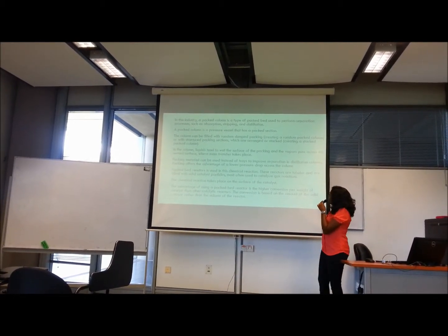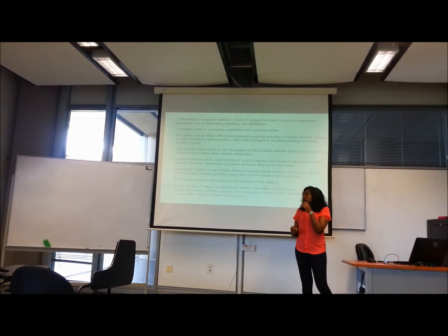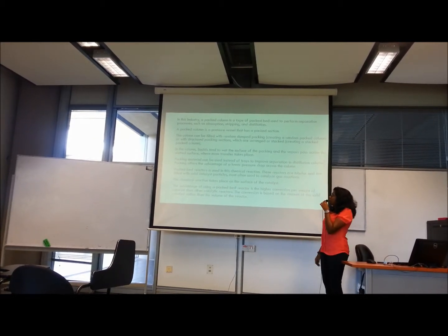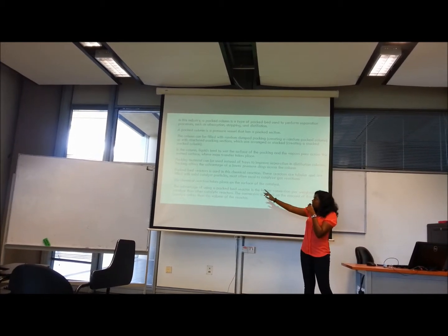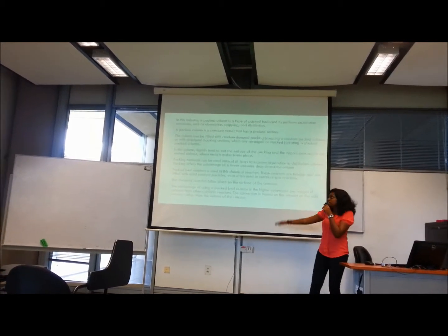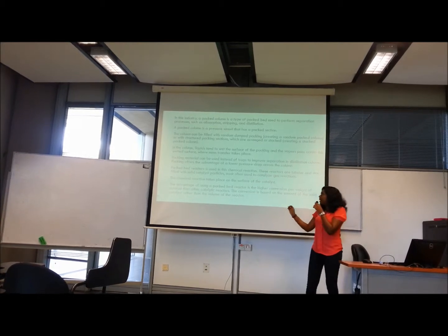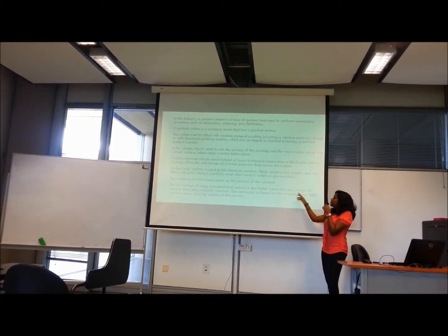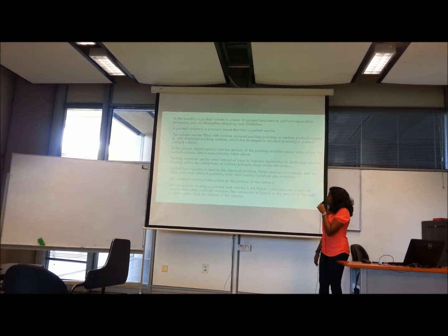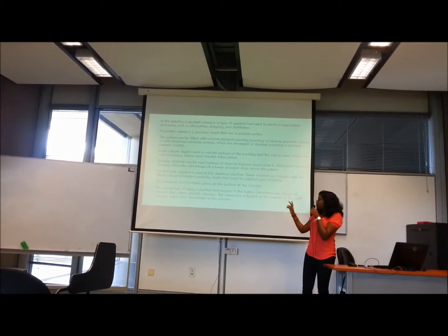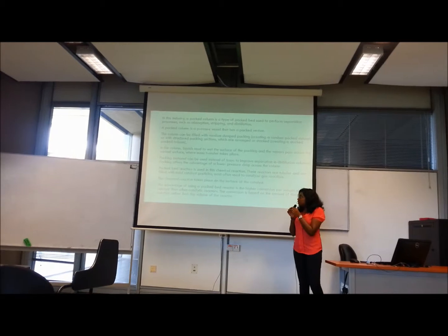These reactors are tubular and are filled with solid catalyst particles and most often used to catalyze gas reactions. The chemical reaction that takes place is on the surface of the catalyst. The advantage of using the packed bed reactor is the higher conversion per weight of catalyst than other catalytic reactors. The conversion is based on the amount of solid catalyst rather than the volume of the reactor.